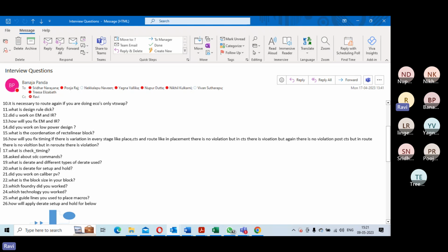Each fan-out should get some minimal current to be able to understand the logic level, not the voltage alone. You have to know your electronics properly. So one of the ways is to reduce the fan-out and split the net.